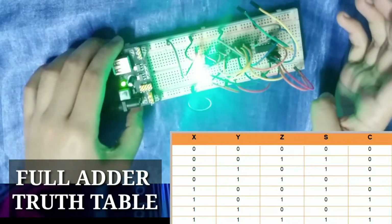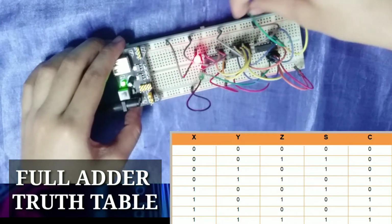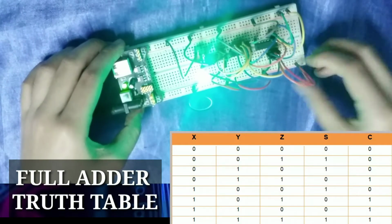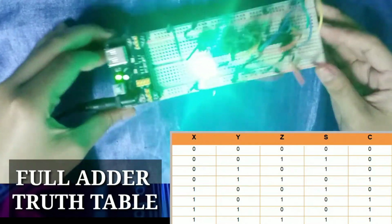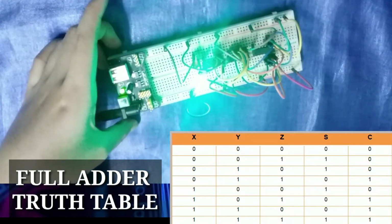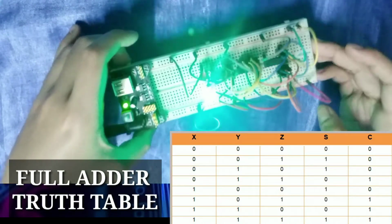Now, if both X and Y are 0, so the yellow and the green wires are 0, and the orange or the Z input is at 1, as you can see, our S output turned on, while our C output is turned off.